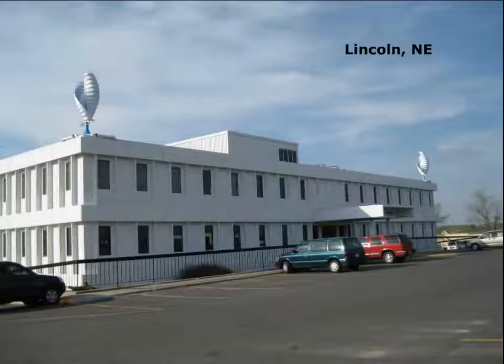And the person finally contacted me back, and he says, to be honest, John, they have effectively produced no power. I will repeat, these 2 turbines have been up for 3 years in Lincoln, Nebraska, and have effectively produced no power. The reason is manyfold. Number 1, they're very low to the ground. Number 2, they're on a building, so there are turbulent winds. Number 3, they are of a Savonius design, so they tend to have very low efficiency, so we aren't expecting them to produce a lot of power.